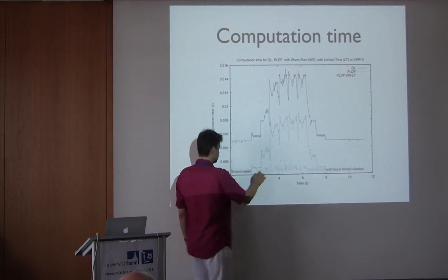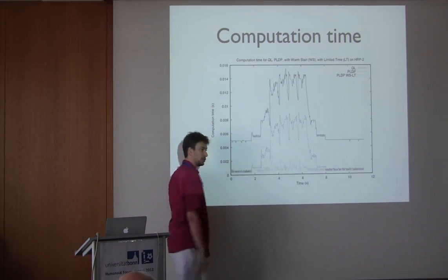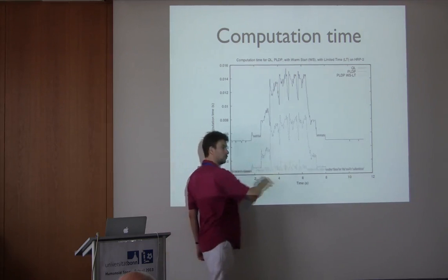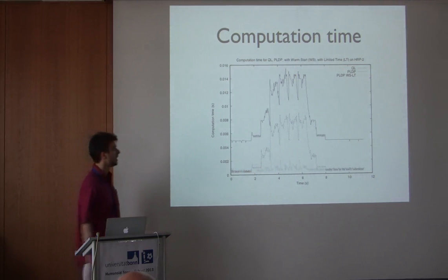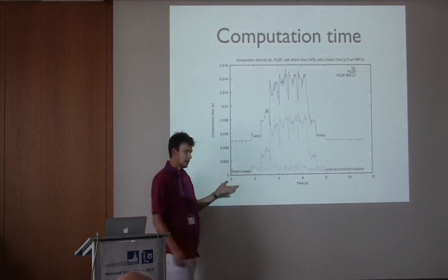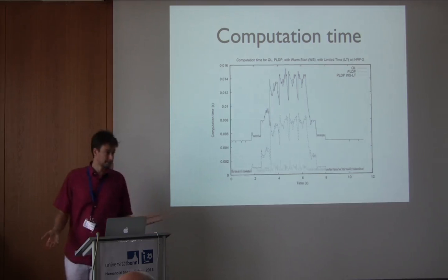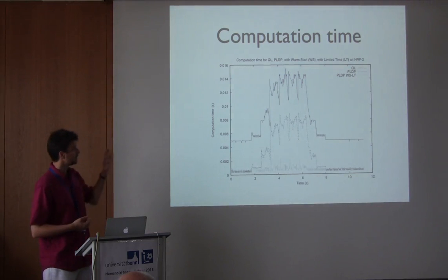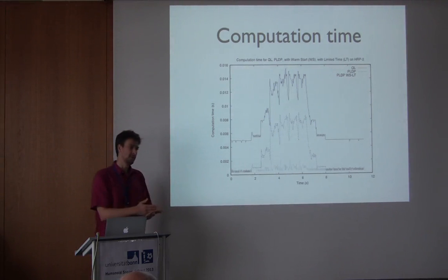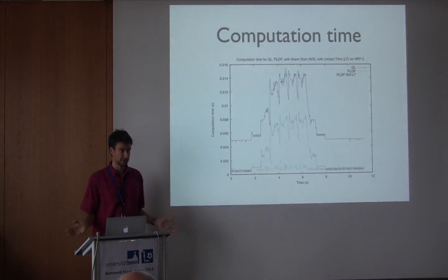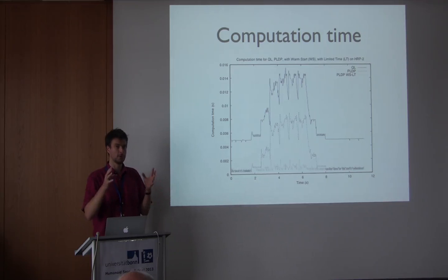Well, of course, let's put a limit on the computation time. Let's say that we just fix it to 2 milliseconds or 2 iterations, okay? Maximum 2 iterations. So what happens is that we stop at the suboptimal point. But you can choose a specific algorithm so that you stop at the suboptimal point, but which satisfies all your constraints. So you are sure that all your physical constraints are satisfied. It's only that you are not making the best choice.